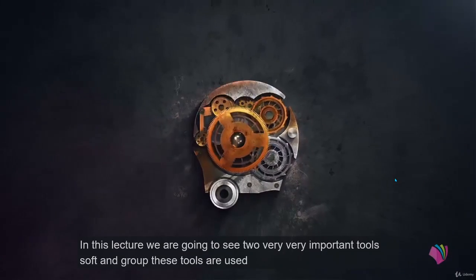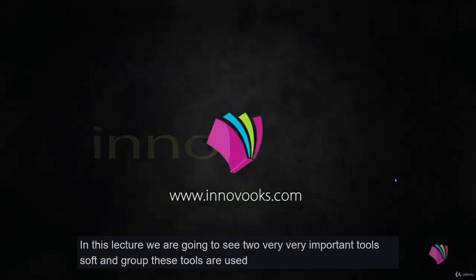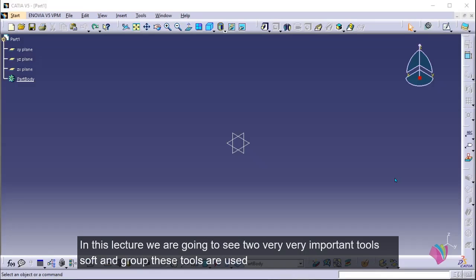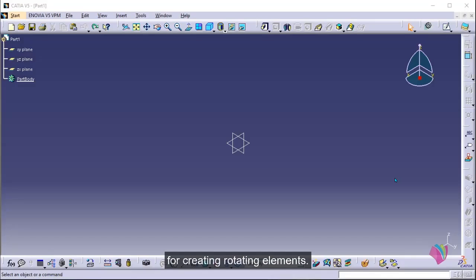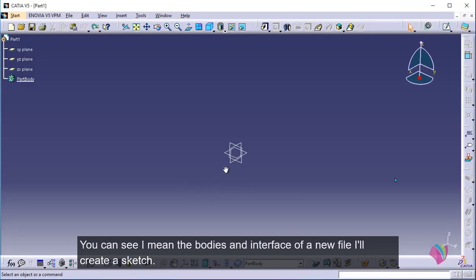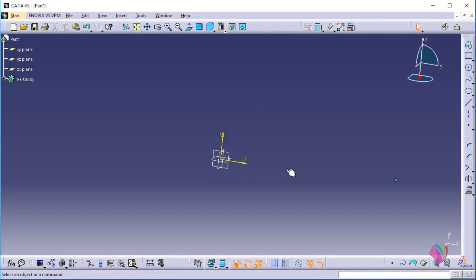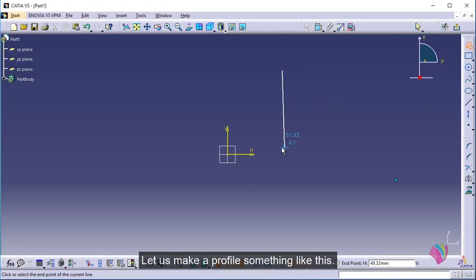In this lecture, we are going to see two very important tools, shaft and groove. These tools are used for creating rotating elements. You can see I am in the part design interface of a new file. I'll create a sketch. Click on the sketcher icon. Click on this plane.